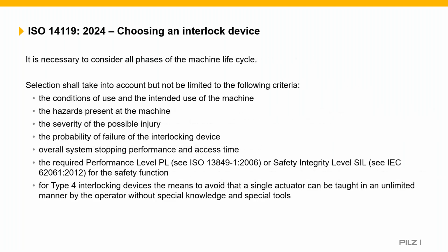We need to ensure that we consider all phases of the machine life cycle. So, what and where is the intended use? Where is it going to be? What hazards are there that we're trying to control? What is the severity of any injury? So, what are the likely repercussions if somebody comes into contact with a hazard?